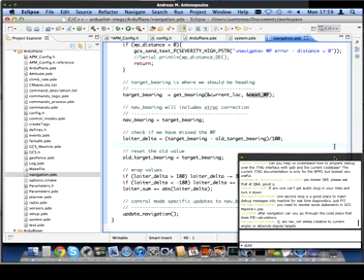Now, there is some code elsewhere in this file that does some slight correction on that navigation bearing based on cross-track, where it adjusts the navigation bearing to be not quite directly at the next waypoint, but instead trying to move us back onto the line joining the previous waypoint and the next waypoint. And that's called cross-track correction.